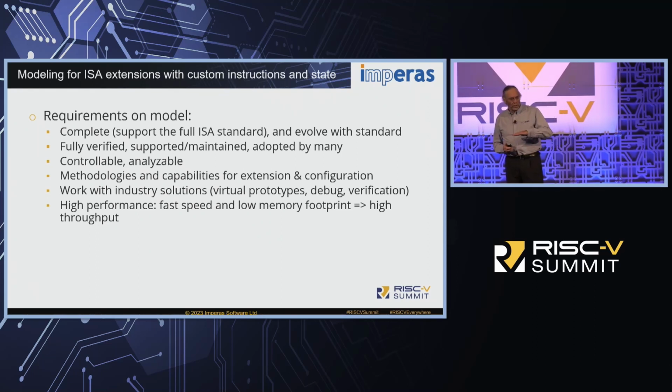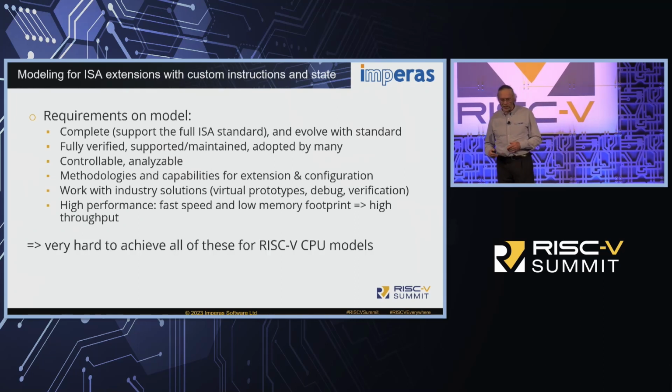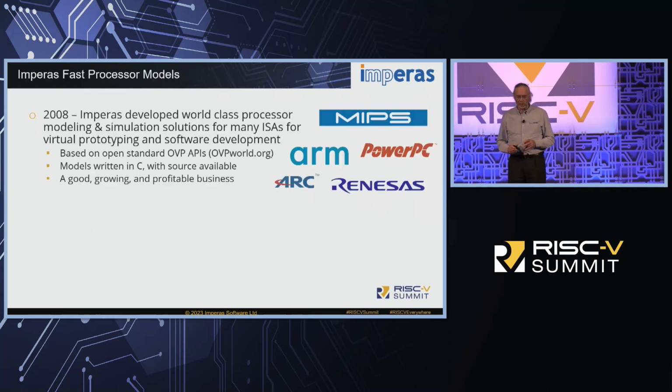And also, a very important thing is, as software is defining these products, you're getting more and more compute in there. I'm not going to use the word AI, I was going to say I'm probably the only presentation that does, but if you're doing modern workloads, you're going to need a lot of speed in terms of the simulation to just run it. Booting Linux on RTL takes 40, 50 hours, so you need high performance technologies. And it's very hard to achieve that. All these different things are pushing the model in different directions as requirements.